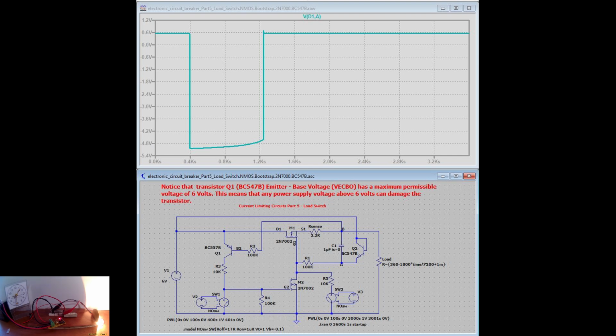This circuit has a peculiarity, which is why it was not used for the high current design. Instead of the diode D2, it used an NPN transistor in a diode configuration. As it shows in the chart, and also in the note, there is a reverse voltage between the capacitor point A and the positive of the power supply, due to the charge of the capacitor.